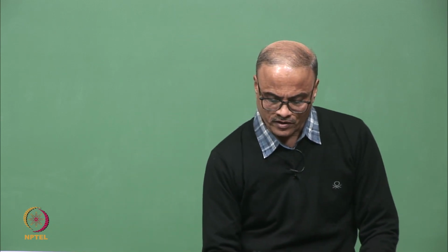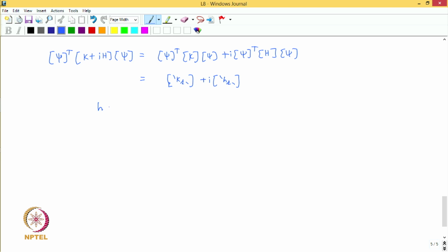For a single degree of freedom system, we just noted that H is equal to eta times K. At the modal level, if we apply this relationship for each mode, then the structural damping coefficient for the Rth mode should be equal to the modal loss factor for the Rth mode multiplied by the modal stiffness for the Rth mode.